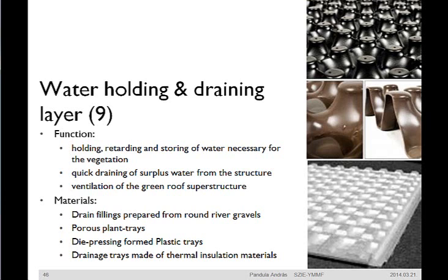And this layer is suitable also to provide ventilation of the green roof structure. Material and element choice for this layer is fairly wide, and in addition to holding and draining of the water, these materials and products are often suitable for performing other functions as well, like filtering the rainwater or providing extra heat insulation.